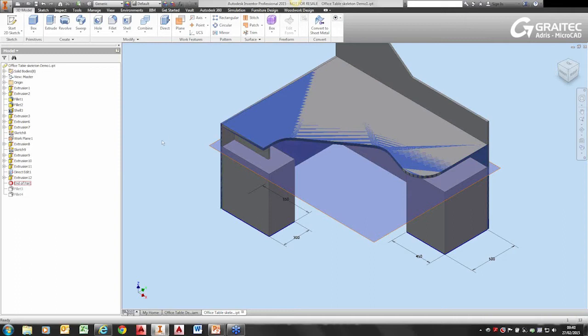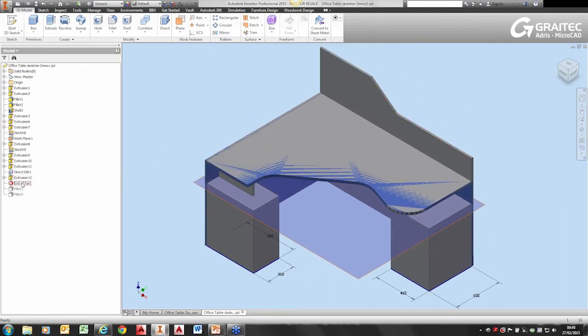So you can see that using your standard Inventor functionality, you can very quickly create a profile that represents your desk, and this one's been done with multi-body solids, and they've been renamed. So these are going to be the components that make up our desk. This one's going to be done using mini fixed joints, but you can use wood joints if it's made out of solid wood.